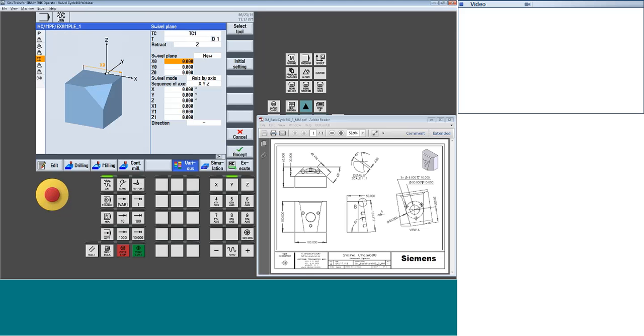But what I do want is I don't want to do the rotation where the 0 is right now, because remember the 0 is up here on the top plane of the part. Once I rotate, that's now going to be in space. And I don't know the distance from where these two straight lines would intersect down to where this plane is. But what I do know is if I drop my Z 30 mil and then rotate, I'll be right on the surface plane. And then I'm just guessing on how much material I'm leaving in the plus, which is a better guess. So I just want to move my Z down minus 30 mil.